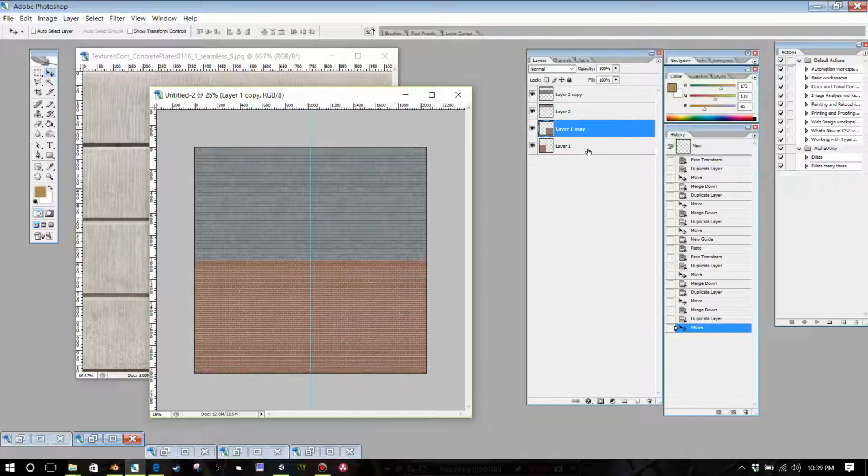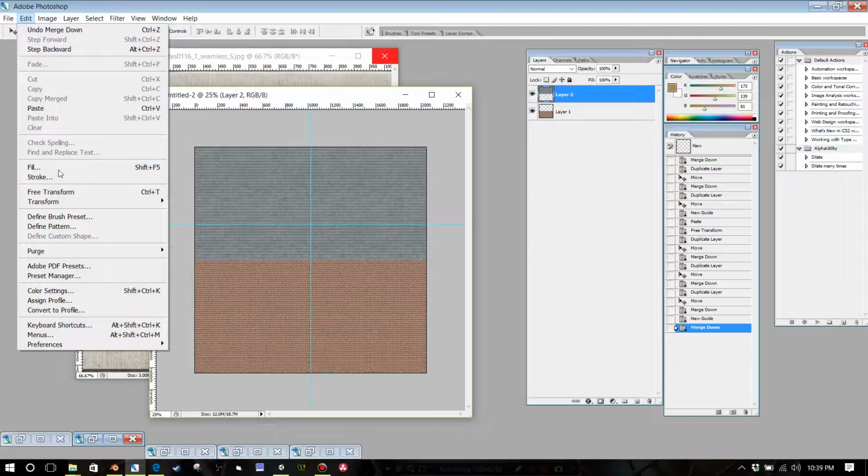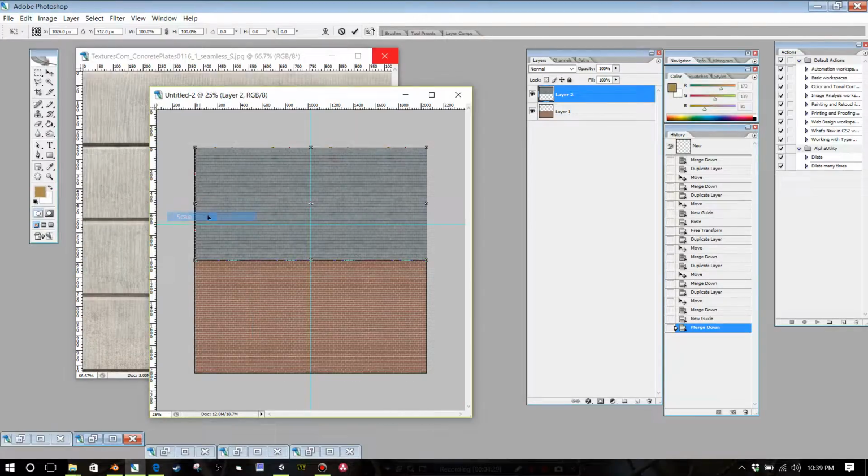So actually we're going to Control E down the brick. The roof, in the end, probably does not need to be this big. I really almost want it like 1/3 of the way. So we can do something like that. But let's Control E the roof, and let's scale it down a little more and do Edit, Transform, Scale. And let's reduce this by 30% or so.